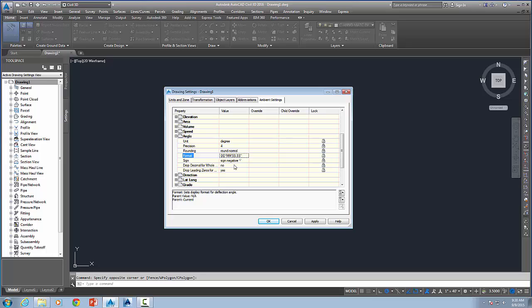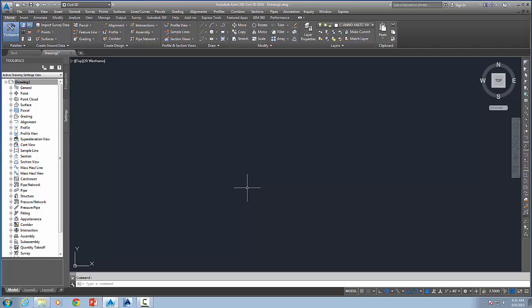So when we enter a number, let's say 30 degrees, 30 minutes, we're going to enter it as 30.30 under this format, and then it'll go in as degrees DMS. If you don't do that, it's going to think that 30.30 is 30.30 decimal degrees, so it will be off quite a bit when you start using angles. So make sure that you change the setting. We want to set that to DMS of that kind. You can do one of these three, it doesn't really matter. I usually just use that one. So we're going to apply that. That's extremely important, and we're going to make sure that we do that every time. Every time you see me setting it up, I'll go into that and show you how to do it.